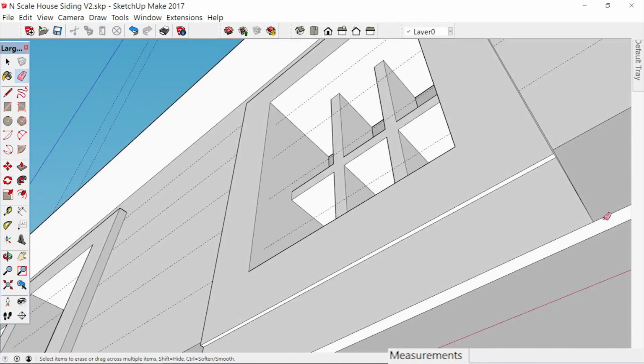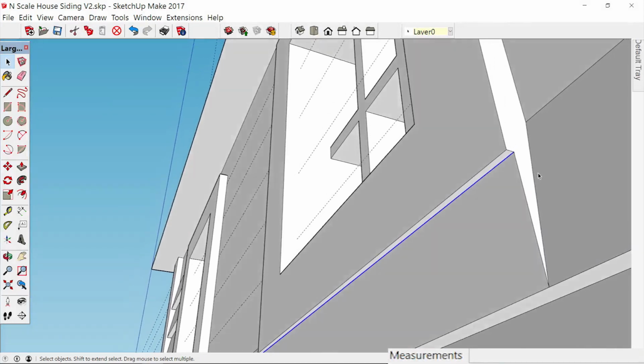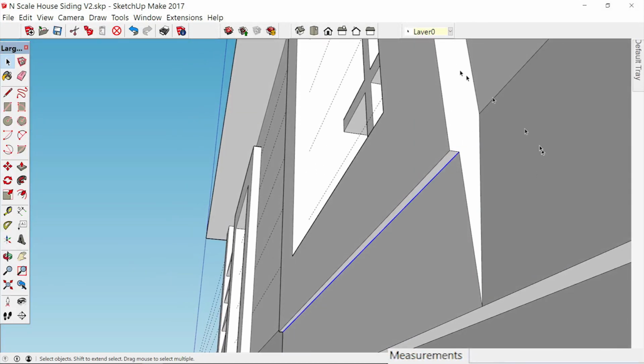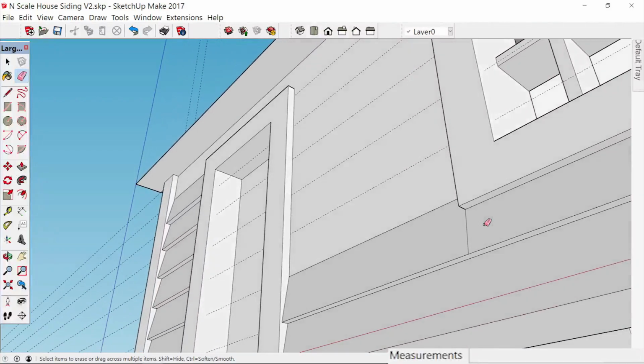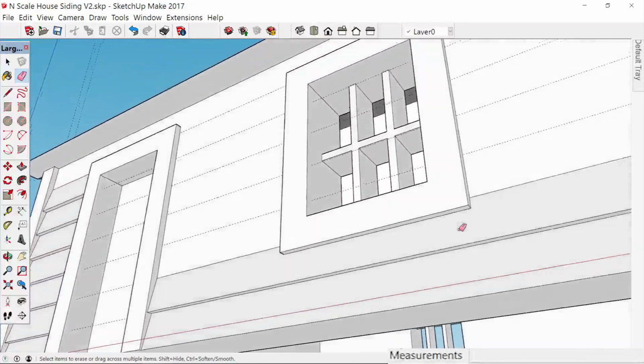But whatever works. All right, select our line. That's the line we're dealing with right there. Now go up here. You might have to zoom in kind of close because that makes it easier to work with because it's bigger. You got further to move it and that kind of stuff. Hit your move tool. You're wanting to move that blue line back until it says on edge. All right. Now, get your eraser tool. Get rid of that. Get rid of that. Now, see how nice that is?